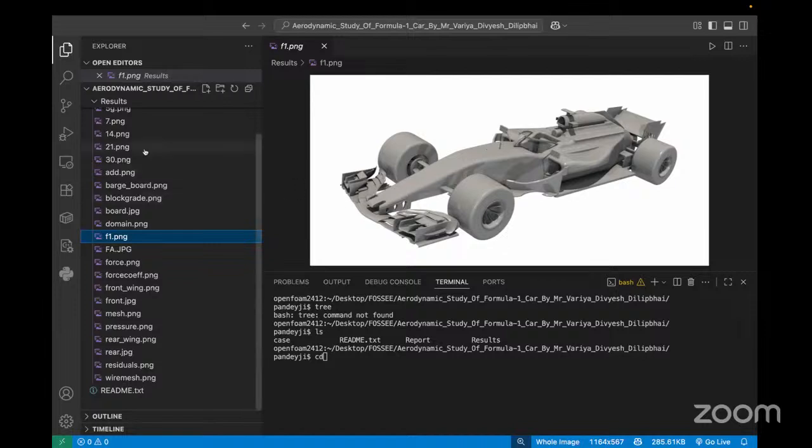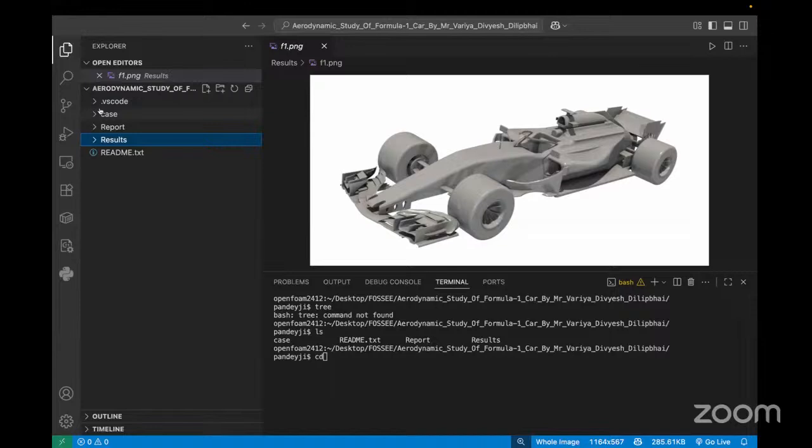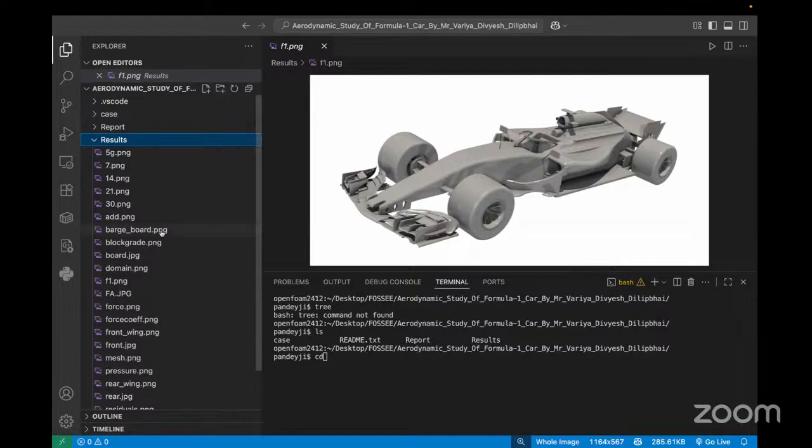The first thing you do, after sourcing a CAD model or drawing a CAD model or a geometry, is move on to discretizing the domain. You create a domain, and then you discretize it, divide it into very fine elements, as you might have heard towards the beginning, what is CFD and all. So I wouldn't repeat much. Let me take you through what are the steps involved.